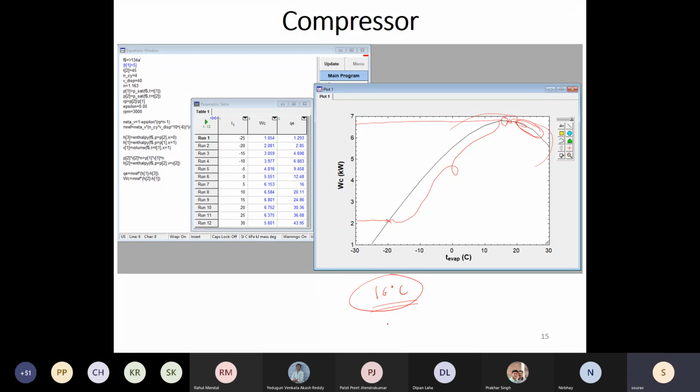So a 1.5 ton AC should demand around 6 to 7 amps of current during steady operation. But if you have those fixed speed compressors, just when it starts, it will demand close to 14 amps. Hence, we connect it to a 15 amps power socket. Whereas the modern inverter ACs can modulate their speed and create a soft start.